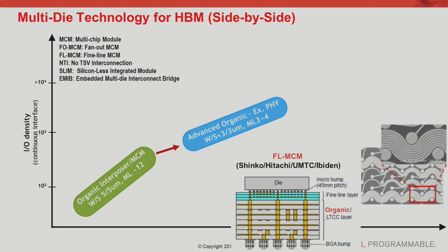And the vias that interconnect the layers also scale down. So if you look at a normal flip chip substrate, the vias could be 50 or 60 micron sitting on a 90 micron pad size. So that definitely reduces your vertical density for routing. So in these fine layers, these vias get down to 10 micron on a 20 to 25 micron pad size.